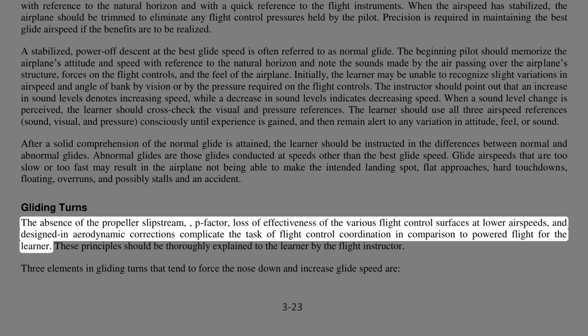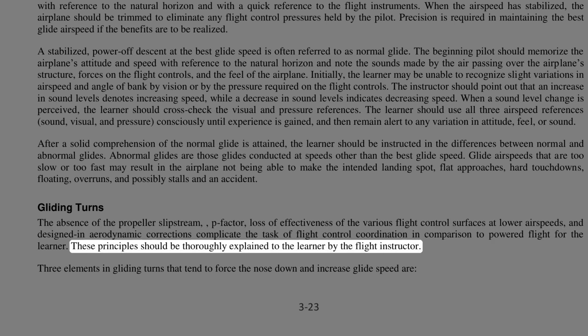Gliding turns. The absence of the propeller slipstream, P-factor, loss of effectiveness of the various flight control surfaces at lower airspeeds, and design and aerodynamic corrections complicate the task of flight control coordination in comparison to powered flight for the learner. These principles should be thoroughly explained to the learner by the flight instructor.